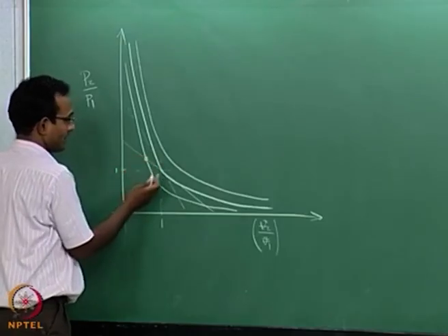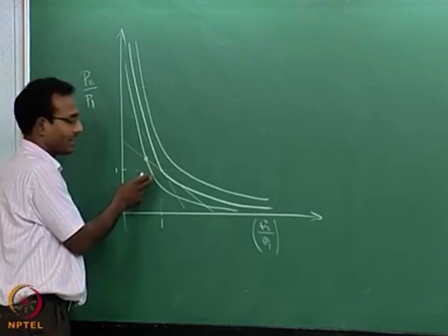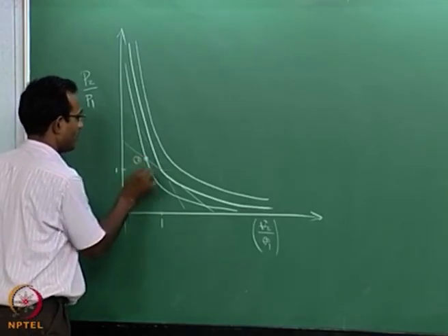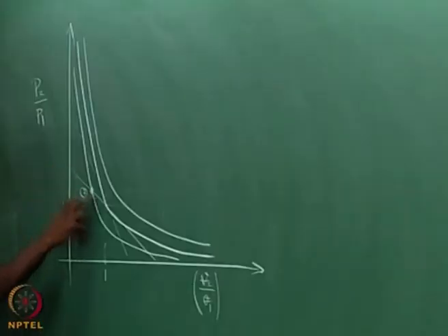If I cool with this particular q value, then I will end up with this particular state 2 for that particular beginning Mach number M1. If I heat it, I find that I am not going to have a solution for that particular Mach number. We will figure out what is happening in detail as we go.